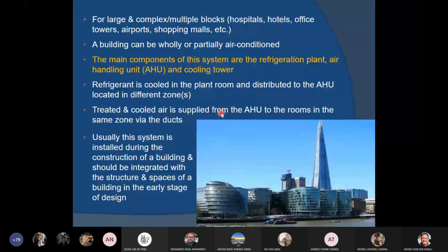For example, two floors can be regarded as one zone, served by one AHU, and another two floors are considered another zone, served by another AHU. This is especially true for multi-story buildings. Now you have many levels, and you can have several floors as a zone.